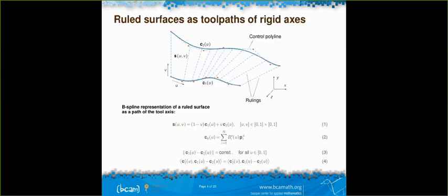Maybe I can intervene. No, this is really just a derivative of the constant length constraint. It says that the projection of the derivative vector at one end is the same as the projection at the other end. So you project these two velocity vectors at the ruling itself, and the projection is the same. Right. So you're basically guaranteeing that the distances are the same just for the sake of what you're doing, even though the ruling does not have to be constant distance.